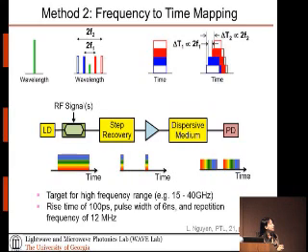So with the time gating, you're able to chop out each of the colors for a tiny period of time, and then you disperse it. After dispersion, all these boxes will be offset because of the different colors. So by determining the time separation of the rising edge of each of the colors, you'll be able to tell what is the frequency of the incoming signal.